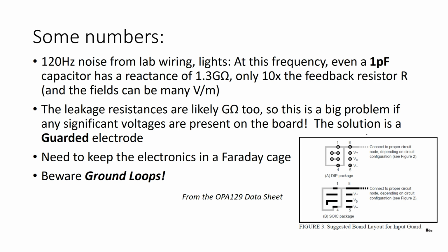So in a funny way, all of the things I've said about high frequency circuits apply to very low noise circuits. You want to keep leads very short, you want to screen things, you want to minimize stray capacitance. Now the leakage resistance is an issue because it's very hard to avoid gigaohm connections between some track on a printed circuit board and, for example, a 15-volt rail.